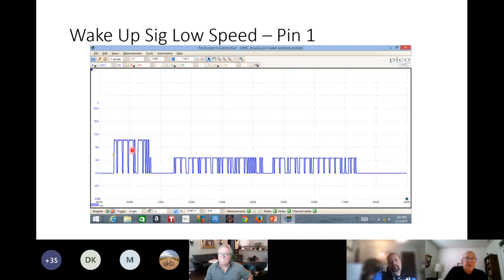If we have the students and the students can get an idea that there is a wake-up signal, why are we doing this? Well, think about this in sequence. We looked at the resistance value of the CAN bus. And we said, okay, it's 60 ohms, that's decent. Well, now we want to make sure that we actually put something through that CAN bus which wakes up all the modules.